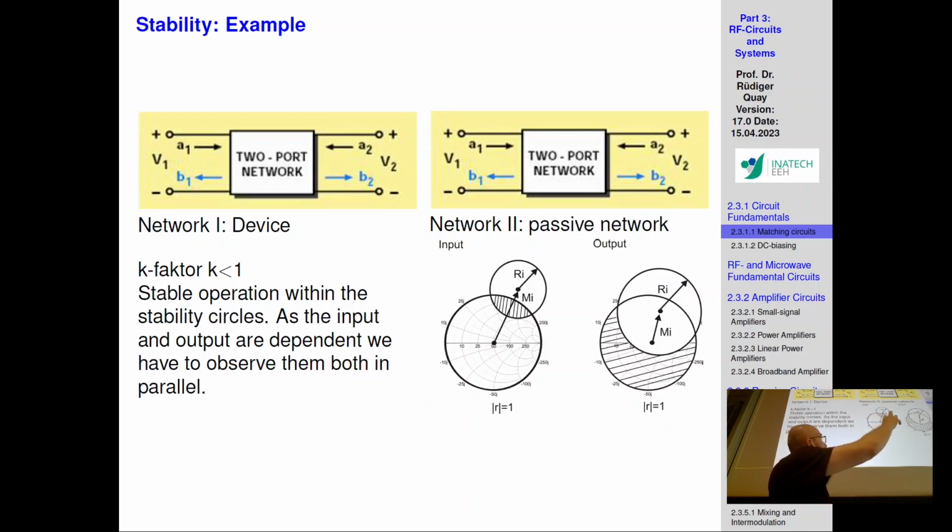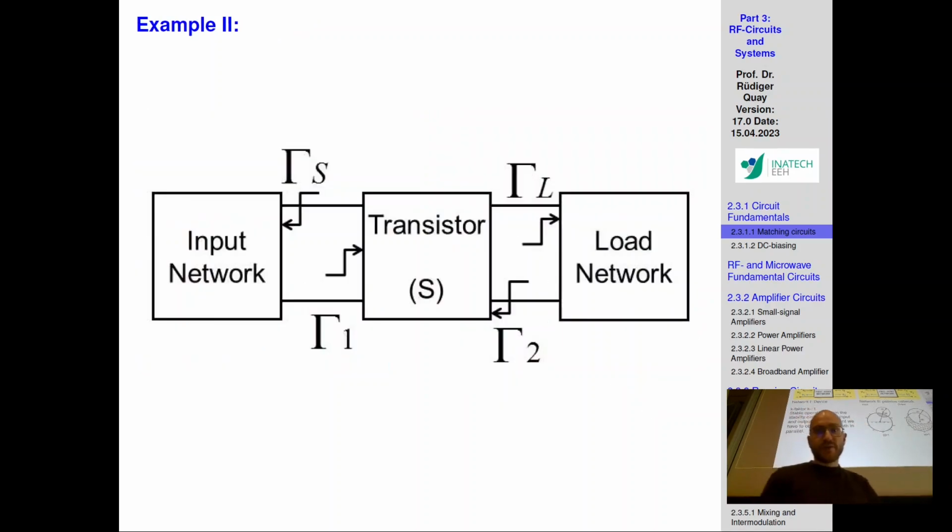In which areas? When you have these areas, a smaller circle for the input and a larger circle for the output where your device is stable, you try to hit the impedance points in that cross section, because obviously your input and output are talking to each other. In that cross section, you'll have the respective impedance points where your transistor will be stable.